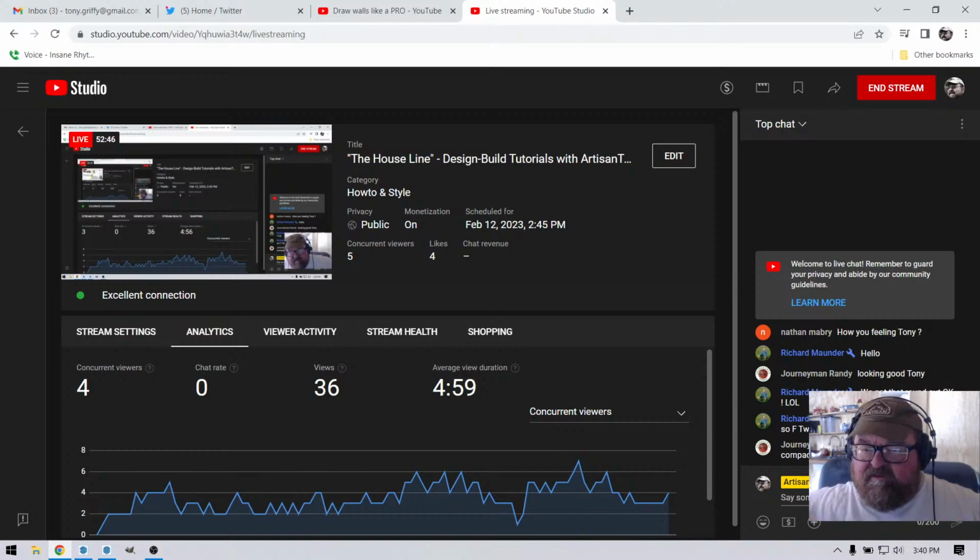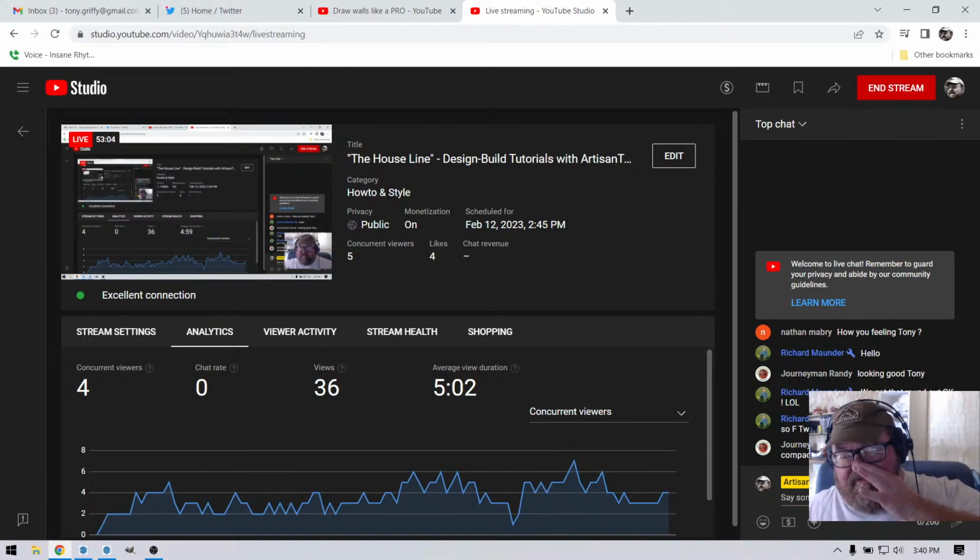The darker soil is your topsoil, and then you get this kind of brownish soil, and you have to get down into the reddish clay. The reddish chert is what we usually find here. And if you have a question, I have a soils guy that does come out and do soils compaction tests, but they're not required on every job.